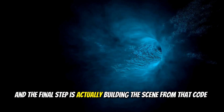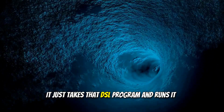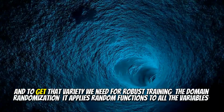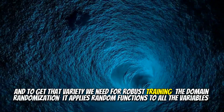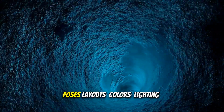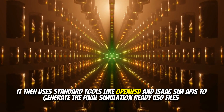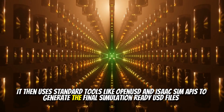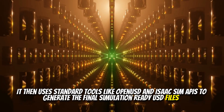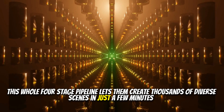And the final step is actually building the scene from that code. That's the results assembler. It just takes that DSL program and runs it. And to get that variety we need for robust training, the domain randomization, it applies random functions to all the variables. Poses, layouts, colors, lighting. It then uses standard tools like OpenUSD and Isaac Sim APIs to generate the final simulation-ready USD files. This whole 4-stage pipeline lets them create thousands of diverse scenes in just a few minutes.